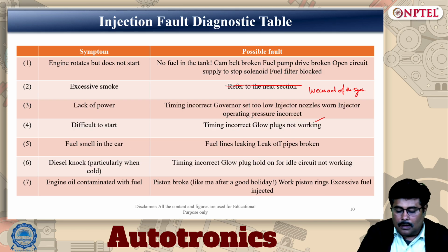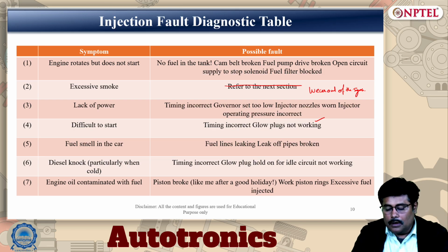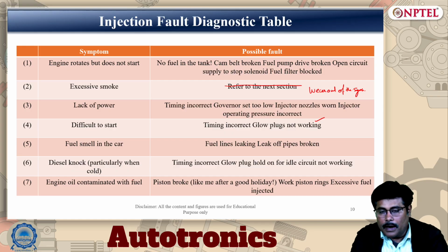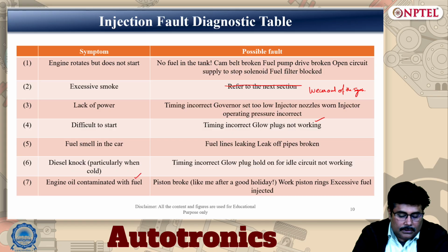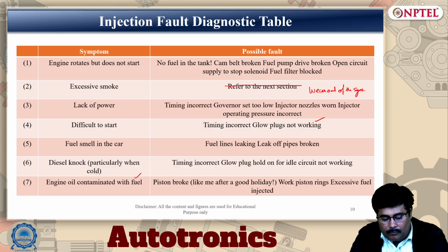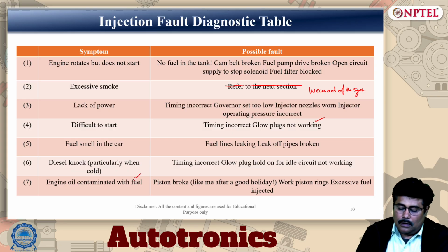Then we have diesel knock, where there is incorrect timing and the glow plug hold-on idle circuit is not working. There can also be engine oil contaminated with fuel, which is due to a broken piston or a worn piston ring, and excessive fuel.